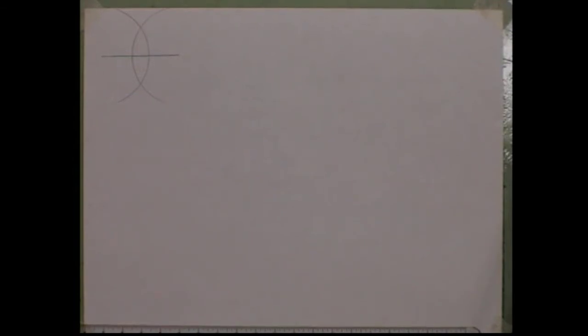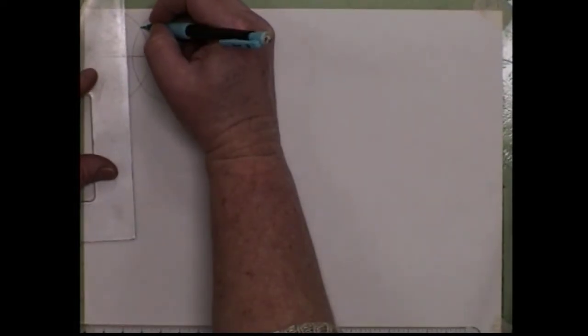So we didn't even have to create this geometry with our straight edge as far as making it parallel with the edges of our paper. We just drew a line. We didn't know what angle it was drawn at. We weren't real accurate other than we know it's a straight line. Then we wheeled our compass out halfway or a little over halfway and struck 2 arcs, one from each side. Now we're going to take our straight edge, because now we have 2 points, right?